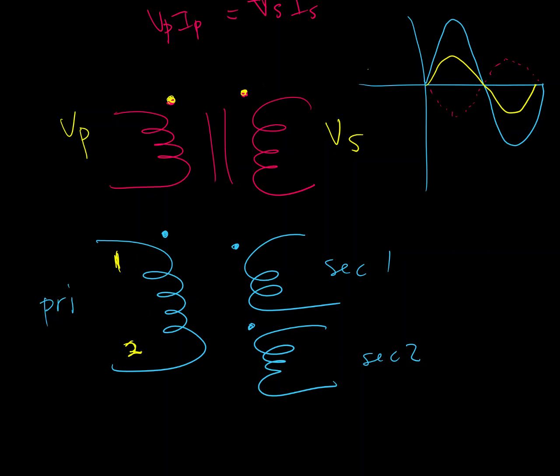Okay, if I get 0, that's a problem, and it means there's something wrong there. But it should be some low resistance value. And between leads 3 and 4 on this secondary, same thing, I should get a low resistance value. And 5 and 6, same thing, I should get a low resistance value.